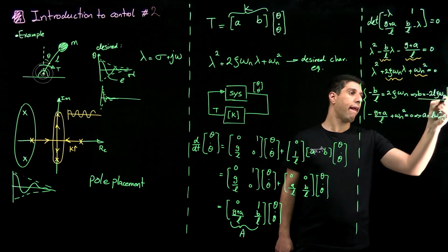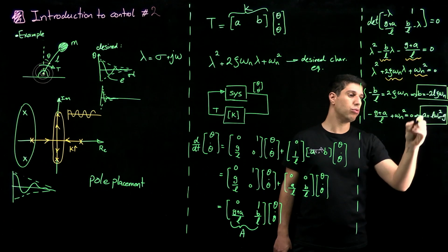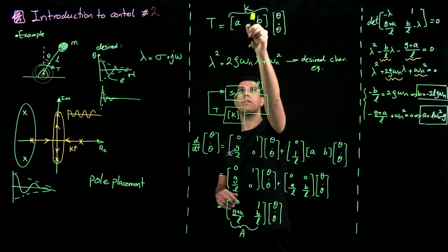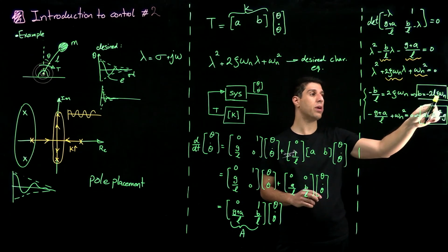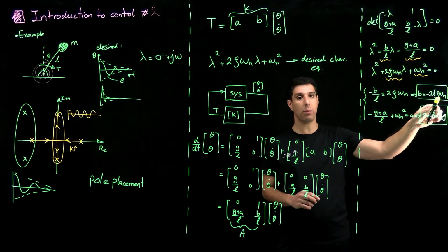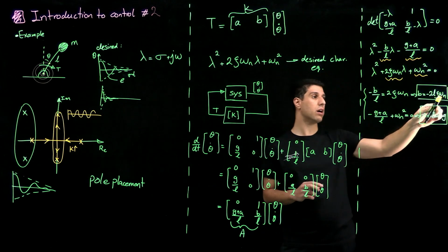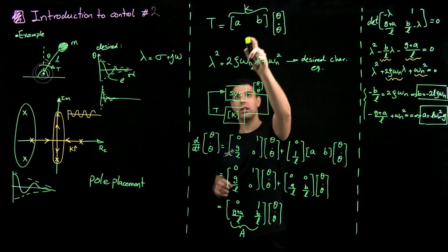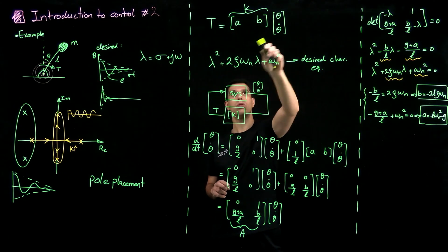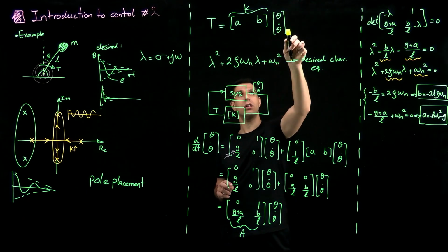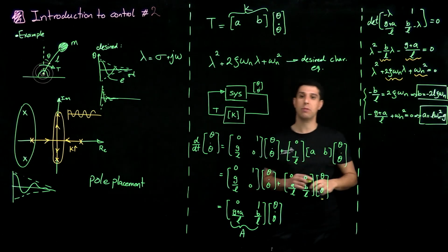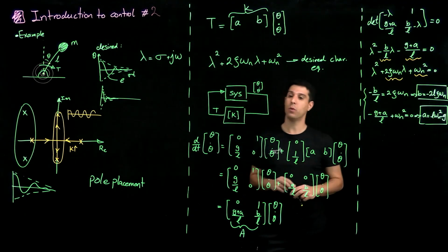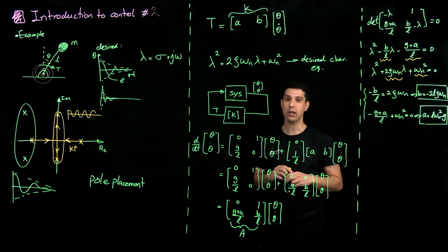So these are my two control gains, A and B, for the full state feedback gain K. If I know my desired damping ratio and my desired natural frequency omega n, I can design B and A and make this feedback control calculation based on the current states of the system, and doing all of that, my system will behave the way I desired.